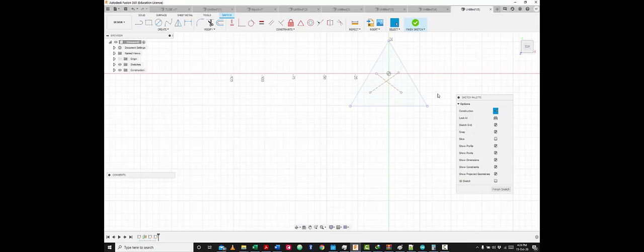And then, good. Now, the next thing I'll do is I want to use these two lines to locate the middle of the projected triangle using constraints. So my goal is simple. I'll make this line locate the midpoint of this line, and then I'll also make this point locate the midpoint of this line, and then I'll make this point and this point coincide with each other.